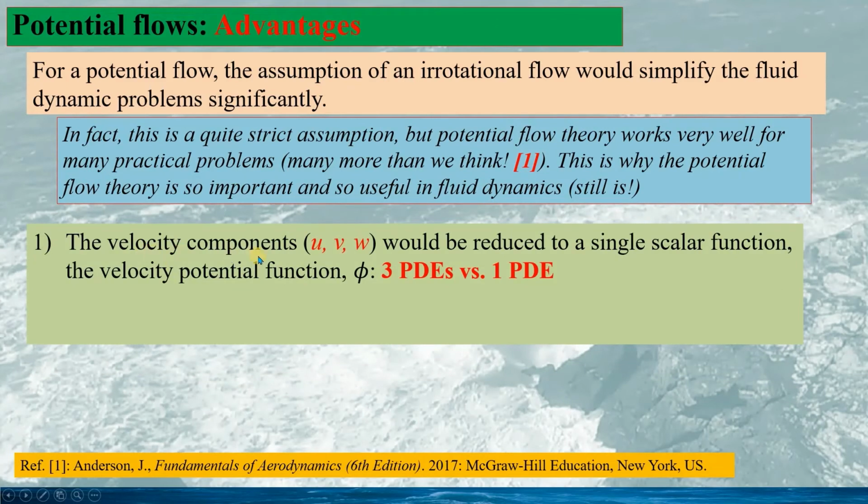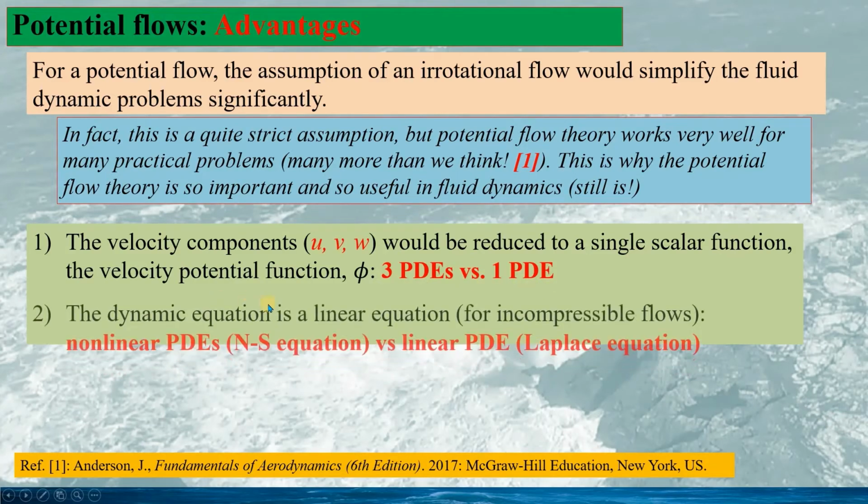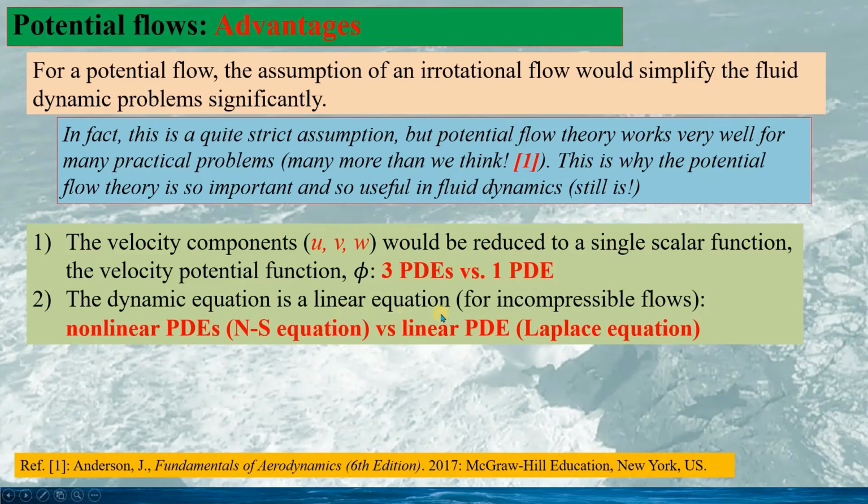So as we have mentioned, with the assumption of an irrotational flow, the velocity components u, v, w would be reduced to a single scalar function. So the advantage would be 3 partial differential equations versus 1 partial differential equation. And the dynamic equation is a linear equation for incompressible flows.